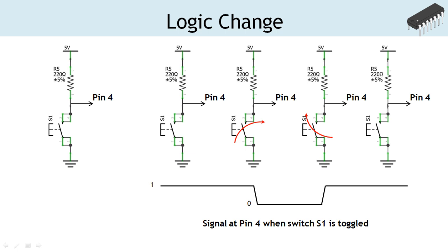And when the button switch is pressed and released after some delay, a pulse of logic low is applied to the pin number 4. Note, the interrupt is triggered only when the duration of the pulse is greater than that of the clock signal. And it must be taken care if the interrupt signal is coming from an external electronic device. But this is not a concern for us.